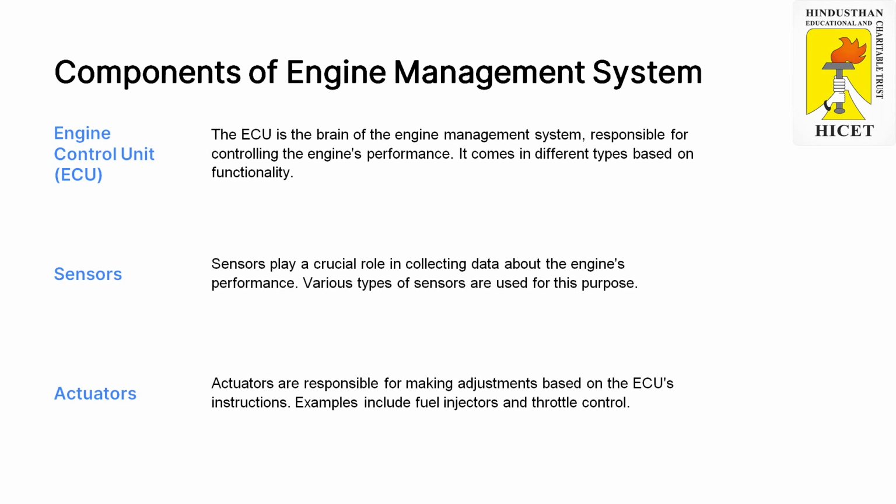That is the master brain for the entire working principle that controls the entire working of the engine, either making an advance function or a retard function, or converting the sensor data into machine language, as well as actuating the actuators, as well as the controller area network, CAN networks. Everything is managed by the ECU. It is just like a microprocessor. This microprocessor controls several microcontrollers. For example, the fuel injection unit has a separate microcontroller that is controlled by this ECU microprocessor.